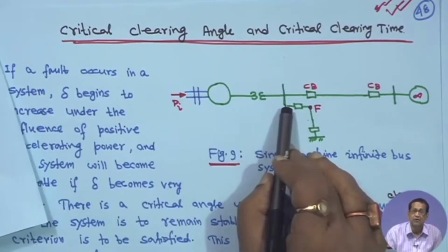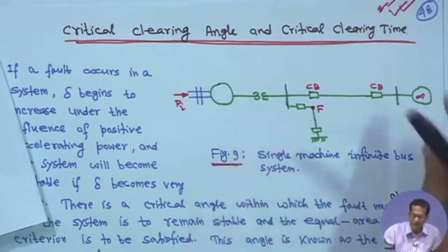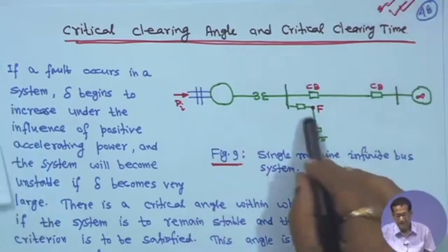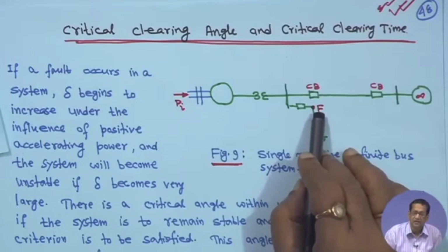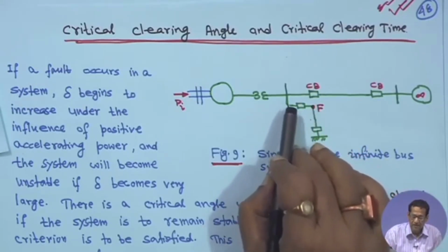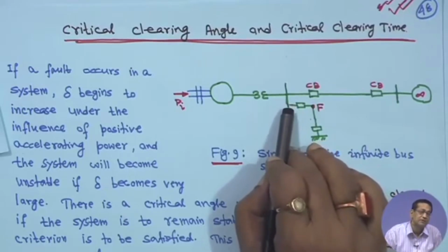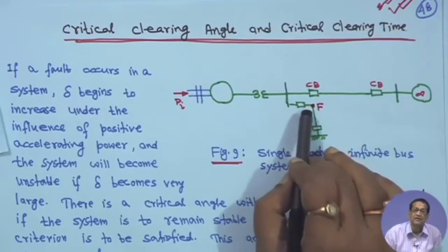If it is 0, then immediately the generator will not generate any power. So, I repeat that this is another radial transmission line and there is a 3-phase fault say. As soon as there is a fault here, the terminal voltage will be 0 till that line is disconnected, circuit breaker trips, right.